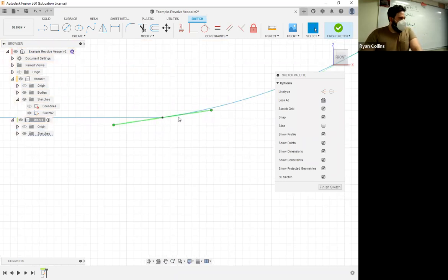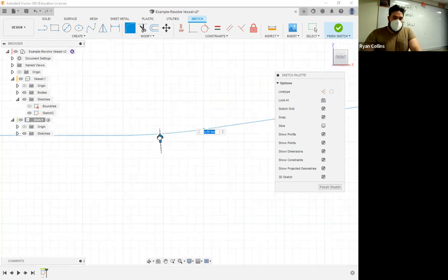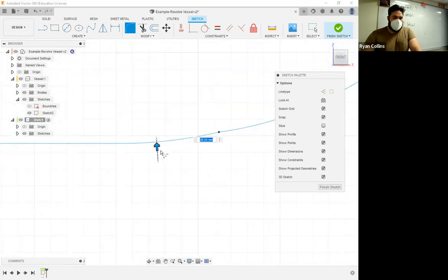Now, of course, the one issue of going from a straight line to a fit point spline, the transition is never that great. You can use the handlebars to try to tweak this, and you can get close. You can get it pretty good. That actually looks pretty decent. But if it is still a little bit wonkier than you would like, one of the other things you could use is the fillet tool. We talked about this last class about how to make a corner curved based off of a radius. It doesn't have to be a 90-degree angle or even close. I can use a fillet tool here. So select there, between these very close lines, and even though it's small, it will adjust and make that line a lot smoother.